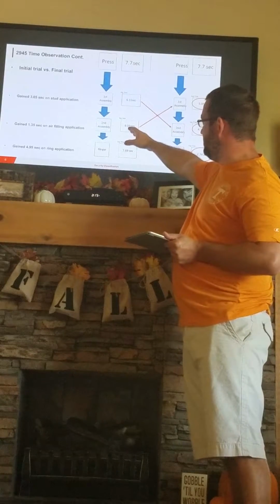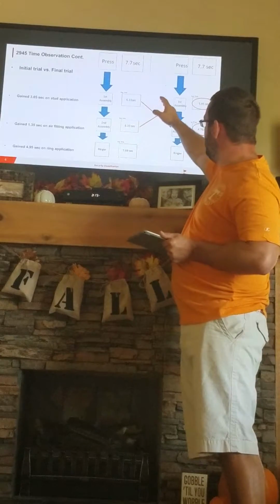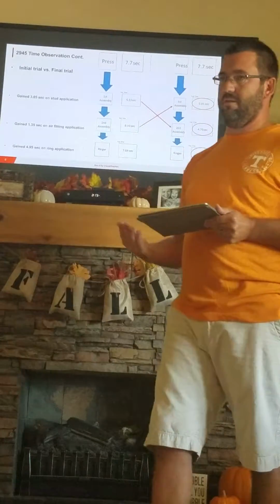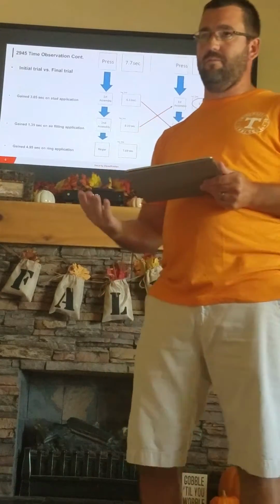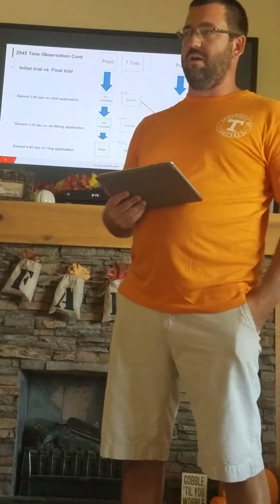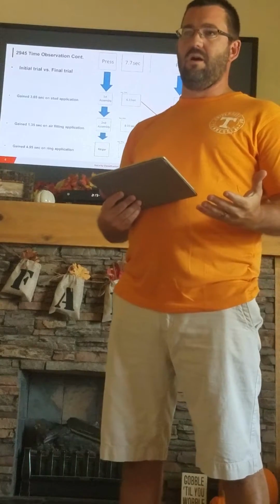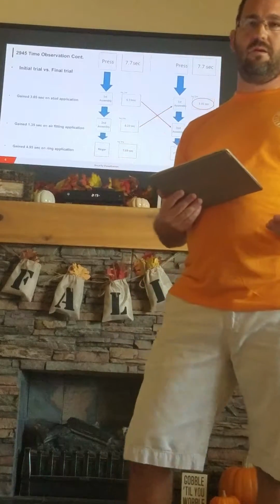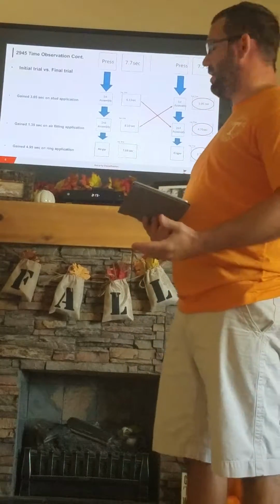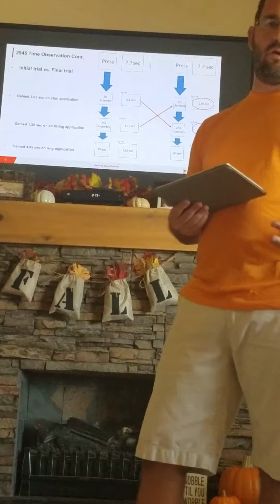So now where you had the air fitting at the first assembly, we repositioned that to the second assembly, the stud application went from the second assembly to the first assembly, along with, like I said, adding the assembly fixture that would drive both studs in simultaneously, the backstop to help correlate the plate, line it up for the assembler operator, and the larger diameter ring.